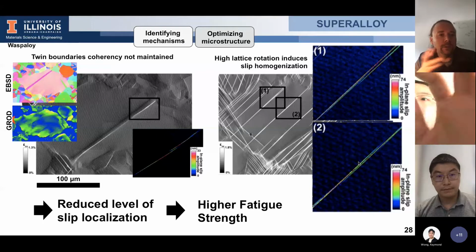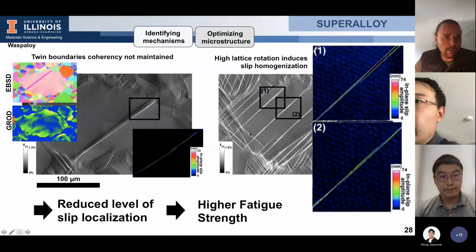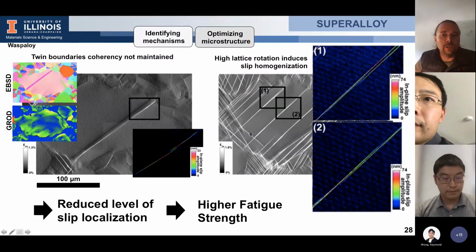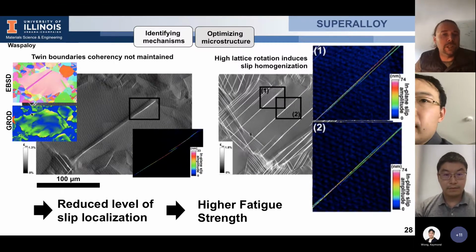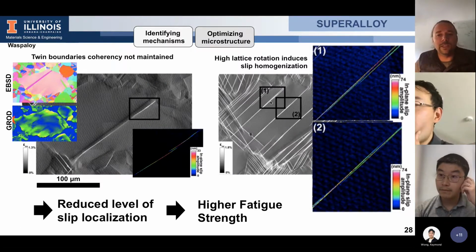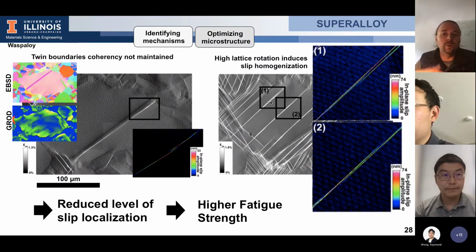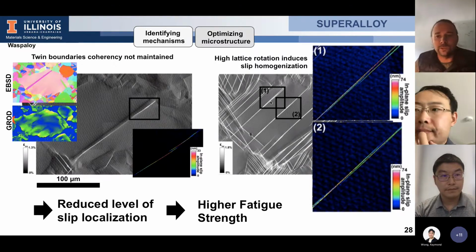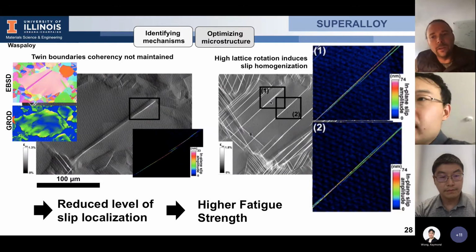Yeah, it's a very good question. So basically, in this alloy, you see this large grain. You have a lot of lattice rotation. You also have SSD, a high density of immobile dislocation. And so when you develop a slip in this large grain, the slip tends to stop in the middle of the grain. Of course, if you are fully recrystallized, because of avalanches and so on, the slip never stops. The dislocations just go. Here they stop.